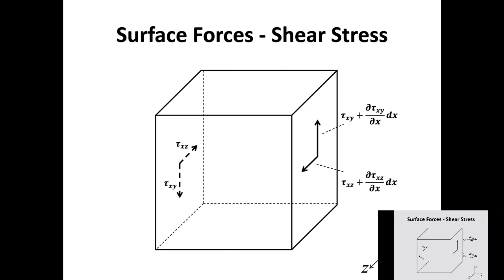And the surface forces now, that's the normal stress, and then you also have the shear stress. So shear stresses on the face normal to the x direction, you have two shear stress components which are again normal to each other, tau xy and tau xz. So those are the directional vectors. Therefore, you have two components on one face. That means on three directions you have 6 components.